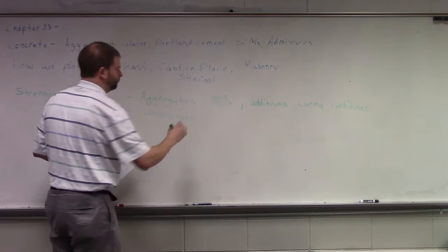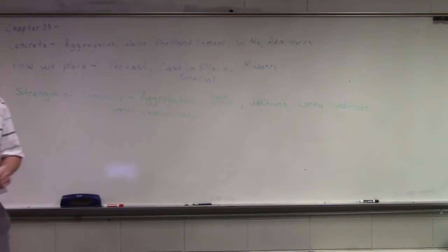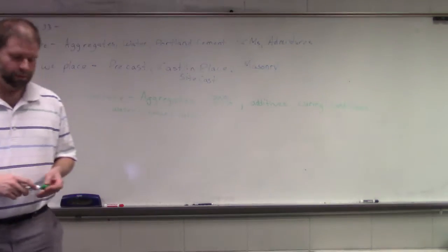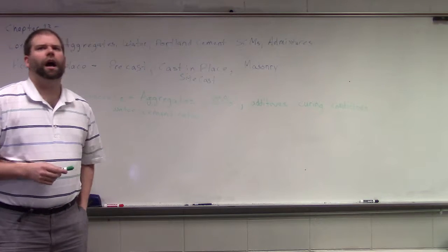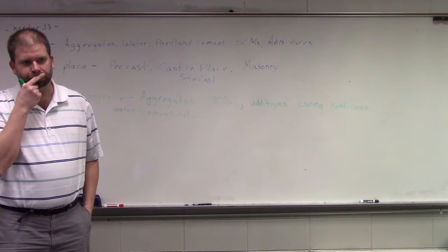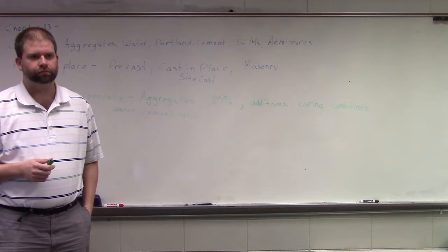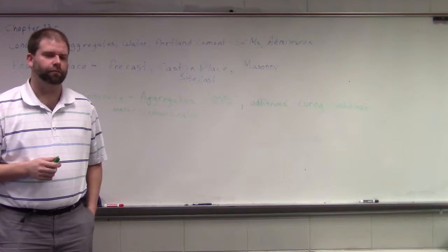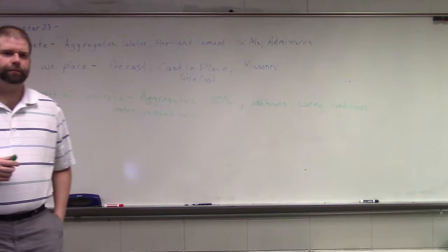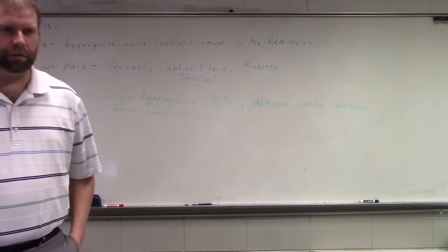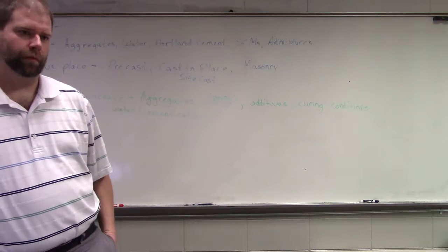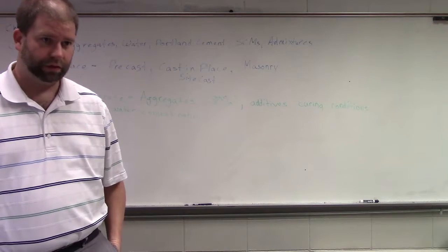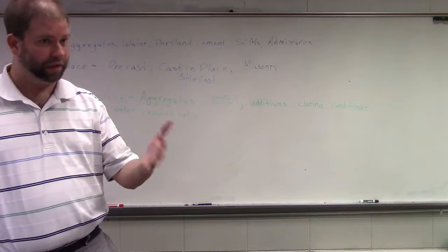So you said the aggregate, like the size of the pebbles, are for different strengths? Because when I was pouring concrete, we had customers who said, hey, I want the little tiny aggregates because they wanted it exposed, you know, after you finish it and then you spray it off, because they wanted that look. And they were doing this on a pretty big patio. So from a patio, I wouldn't be concerned about the strength component of your aggregates. Okay. There you're looking more at a finish aesthetic, right?